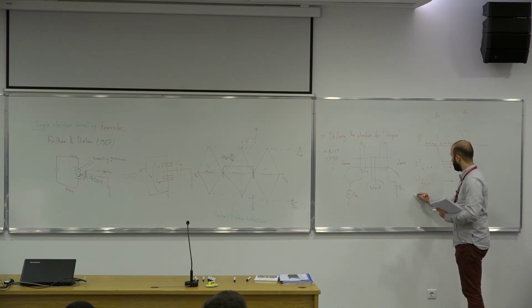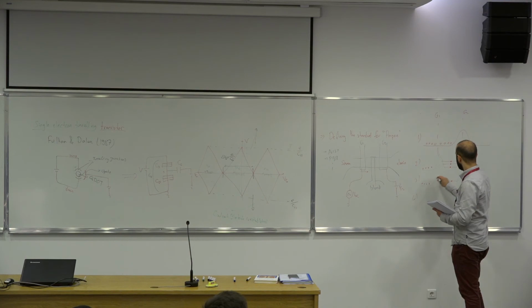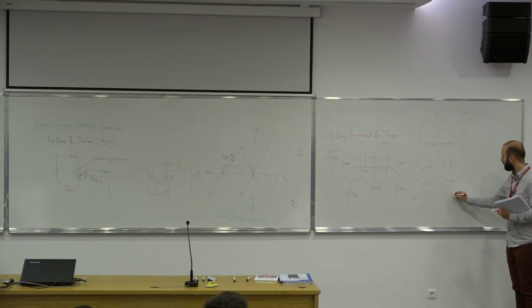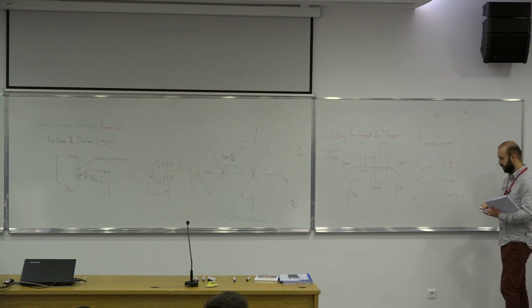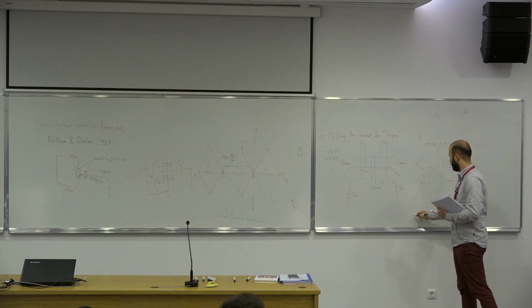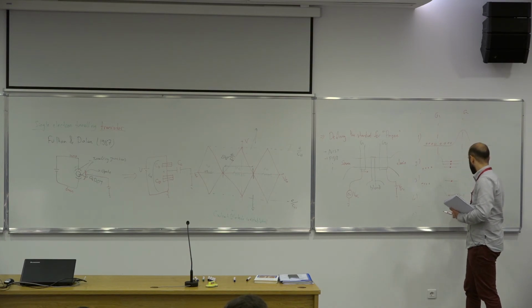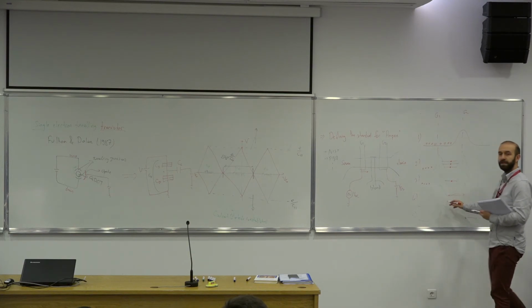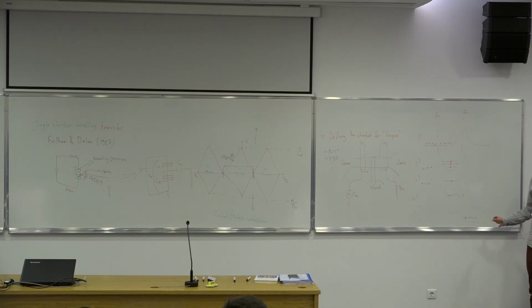Then in the 4th frame, you keep increasing the bias on G1. So this electron can no longer stay here, but tunnels through this potential. So in the 5th frame, you end up with basically a landscape. So you simply transferred a single electron to the right-hand side of this structure.